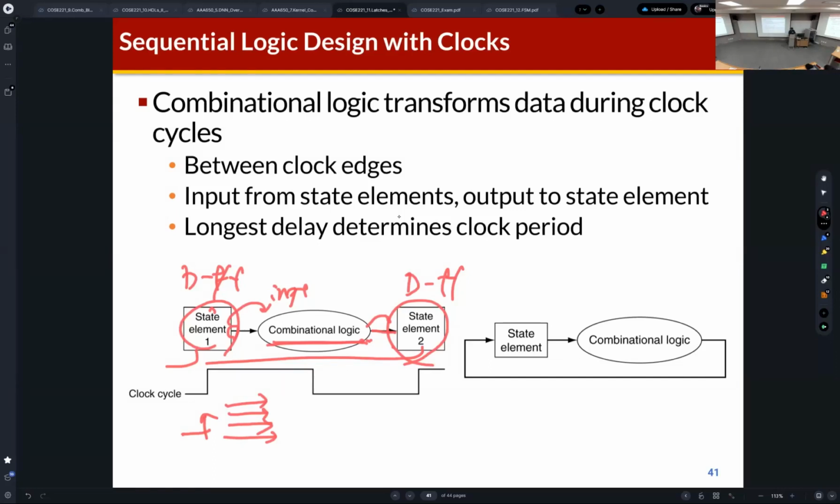And the output delay may be different, because it's combinational logic, but this output is just sampled, which means synchronized, just at this rising edge of the flip-flop. By doing this, we can generate a stable and controlled system. And usually we implement the digital system like this.